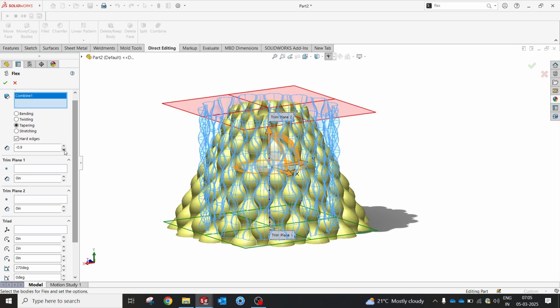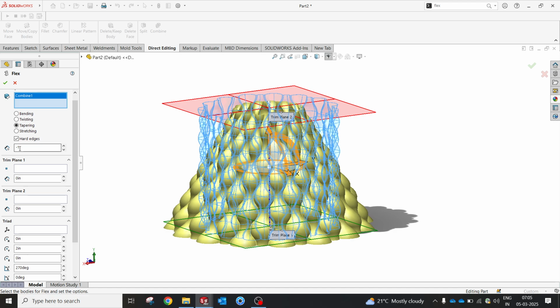So according to that, the 1 minus 1 and select OK. You have to make sure of the axis and the dimension, how much taper you prefer as the factor. So I'm selecting OK now, so that my overall geometry from cylindrical will become a taper.